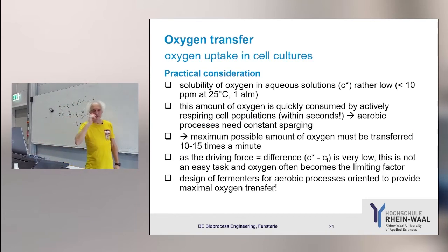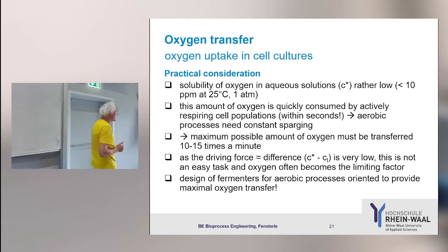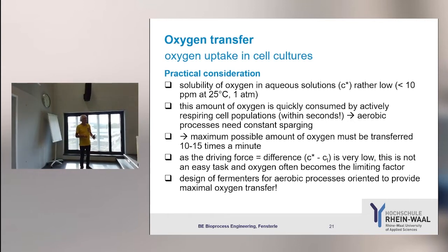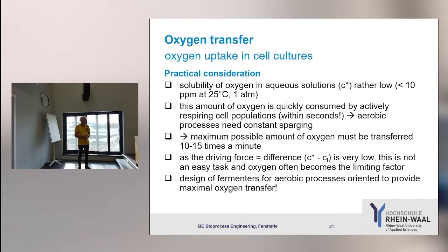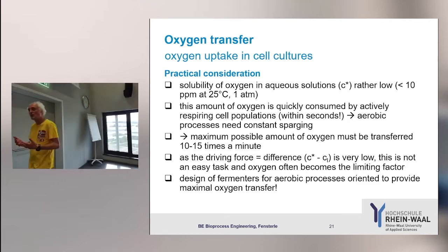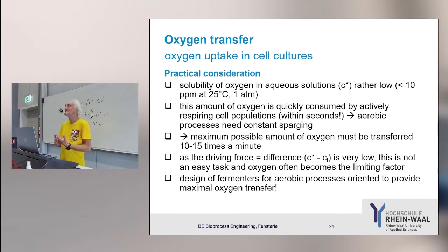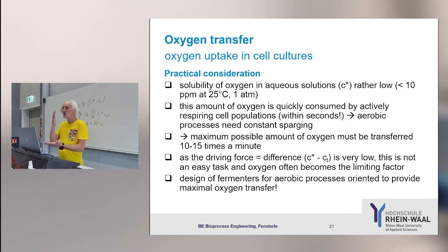So a very big problem with oxygen, of course, is that the solubility of oxygen in the liquid is low. And this, of course, doesn't make us too happy, because this means that we cannot put in the oxygen at the beginning, close everything and wait. So this means that even if we have to provide all oxygen which is required, it is consumed within seconds.